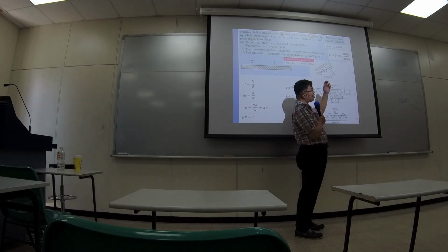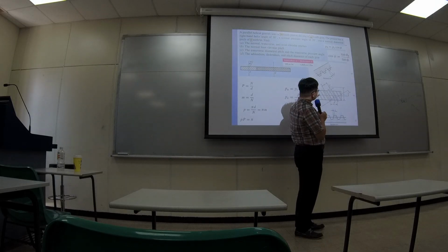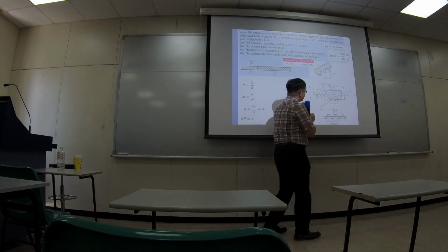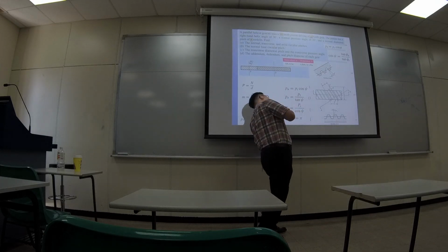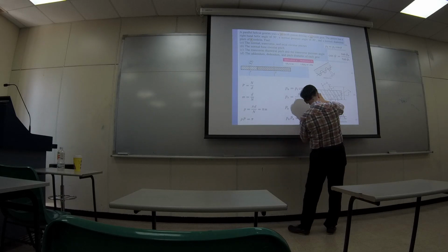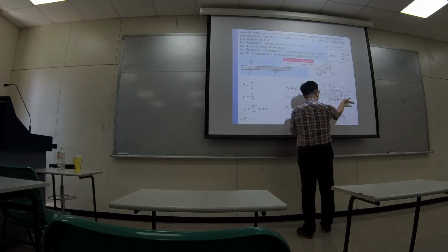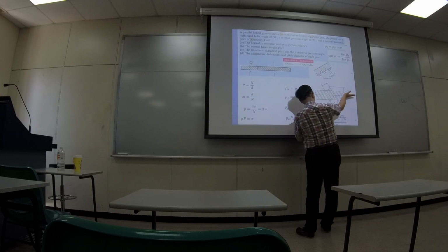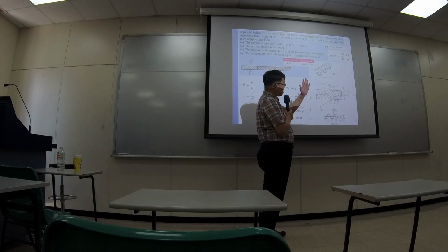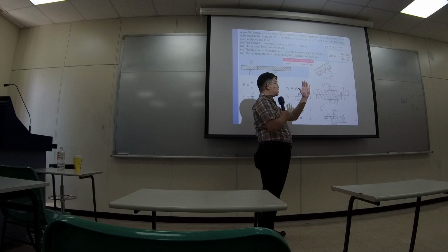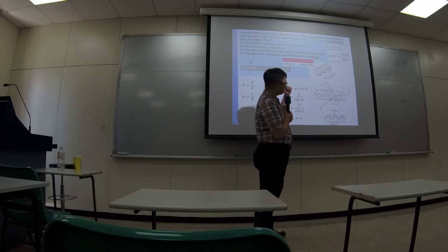Now, similar to what we mentioned earlier about the angles, but this time you tilt your head and observe the teeth along this way. And the angle of your tilt is exactly the helical angle, how much tilt you have for your helical curve.